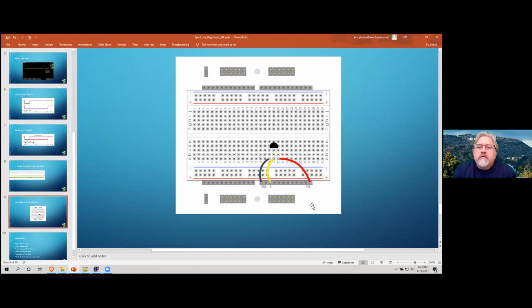Remember, we can tell the Propeller to add a pull-up, so we don't need to have one externally. If you were using this with a P1, you would connect a 3.3K resistor between the middle and the power supply to add the external pull-up.